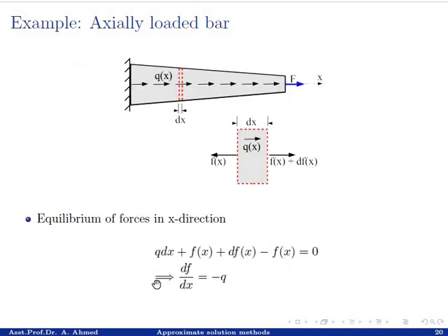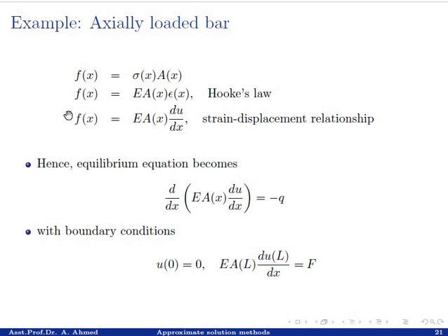For example, in this particular case, I know that the displacement of this bar is 0 at x equal to 0, and at x equal to L, it is subjected to some external force F. So right from this equation I can say that at x equal to L, the internal force must be exactly equal to the externally applied force F. These are the supplementary differential equations that need to be there in order to solve this equilibrium equation.